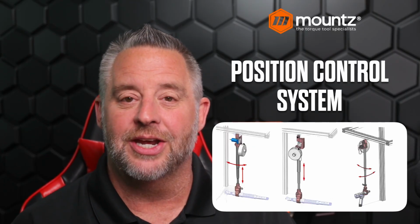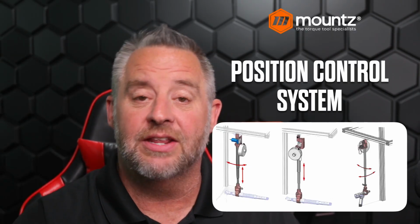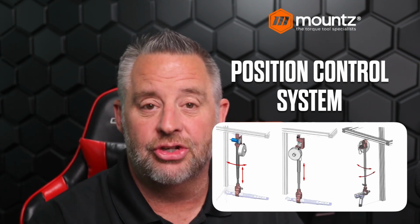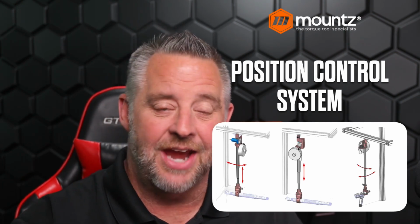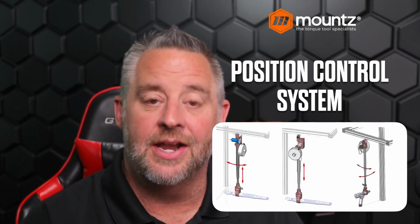Now there are a few different encoder type positions that we can use here. One would be a length encoder that monitors the length of where the tool is in relation to the fastener. We could also add a rotational encoder there to monitor the angle of the tool. We can use those in combination of each other, so an angle encoder and a length encoder.